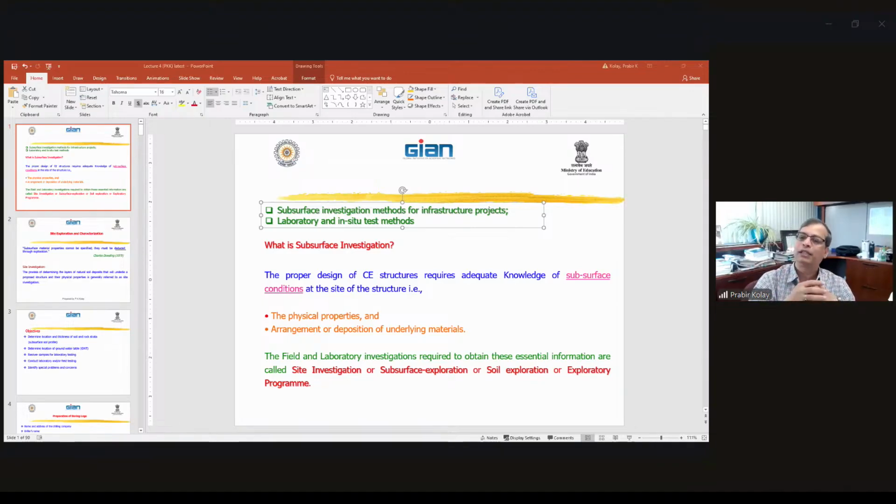So in most cases, the SPT value is easy. The instrument is cheaper. You just hammer it, ignore the first 6 inches, then another 6 inches, count the number of blows, and you will get the SPT number. Obviously, you need to do the correction. Depending on what type of hammer you use, the efficiency of the hammer, either 60% efficiency or 70%, you can do the corrections.